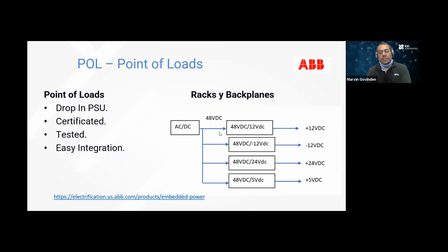And from there, on those two boards, you distribute the power into the power lines you need on the board, which could be 12 volts, minus 12 volts. You're thinking of op amps, if you have op amp circuitry. You could have 24 volts or 5 volts, 3.3 volts, and you distribute these out on lines on the backplane. So some of the boards can be almost dummy boards. They just get power straight from the connector. And that way you centralize the power in that tributary. So it's very good, it's certified, and you can maximize on volume.